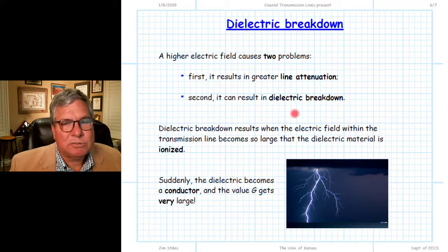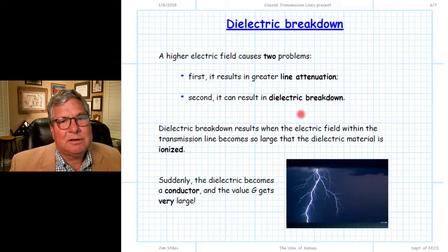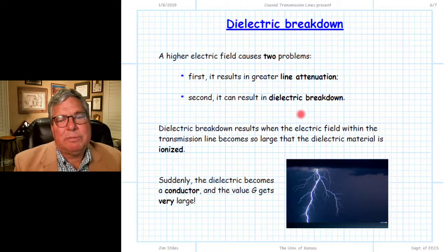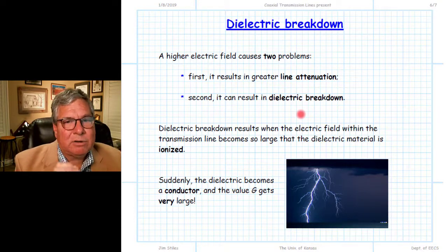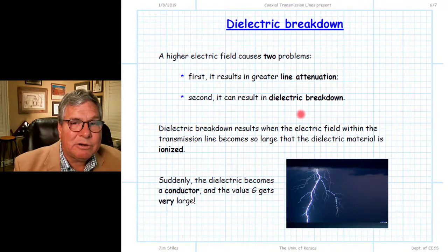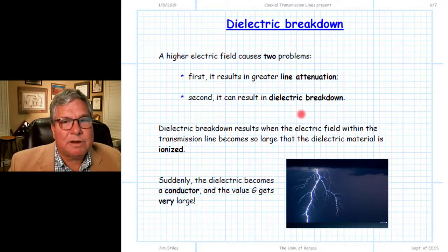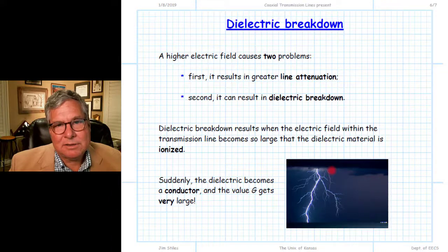And this is just one as we try to put too much power down our transmission line, propagating down our coaxial transmission line. Of course, the voltage between the two conductors will increase, and because of that, the electric field between the two conductors will increase. As we increase the electric field, the dipoles within the dielectric will begin to stretch. They'll begin to polarize, and they can only stretch so far. It's like stretching a rubber band. The dipoles in the material in the dielectric, at some point they stretch and then they break. And we're very familiar with this phenomenon. It's exactly what happens in lightning.